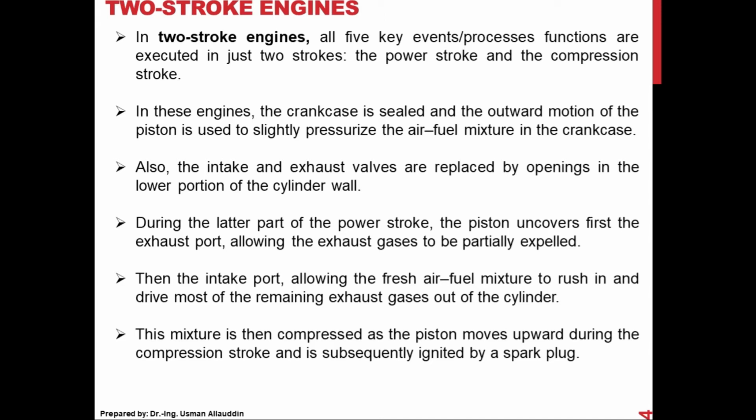So these are the two key events, two processes. Then the cylinder will be filled with the exhaust gases. The piston will again go from bottom dead center to top dead center, but in this process the exhaust valve will be open, and all the exhaust gases will go out of the cylinder.